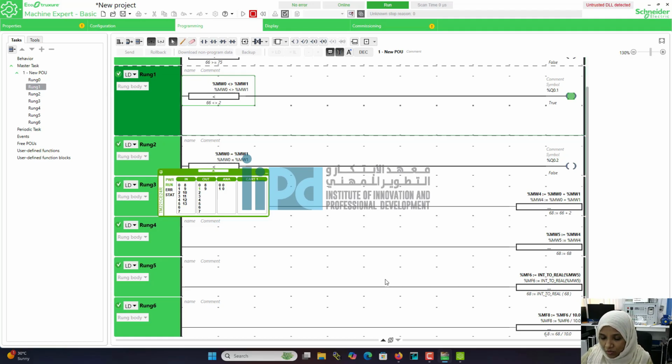Whatever range you want, you have to create it using the mathematical instructions. In that case, even the point values are important. Sometimes in your sensors, if the values need fine adjustment like 2.5 or 3.5, you have to go for the float instruction.